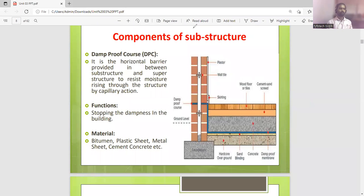Next, after the plinth, what is the next point? That is superstructure components. First of all, what is a superstructure? The structure which is above the ground level is called the superstructure. What is the first one in it? DPC. What is DPC? Damp proof course. Look at a building structure here. This is your foundation level.